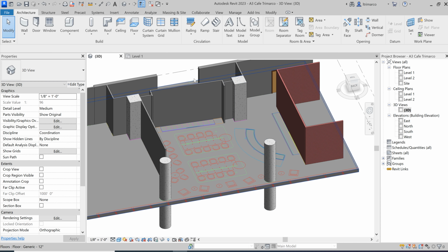Now, if I was going to build these cabinets custom, literally based upon a design, based upon a sketch that I sketched out, I definitely would be heading to Model In Place. But I'd like to show you what comes out of the standard software package of Revit first. So Place a Component. Right away, that family automatically is loaded. For the most part, you open it up, and it'll tell you the title, Double Door, 2 Drawer.